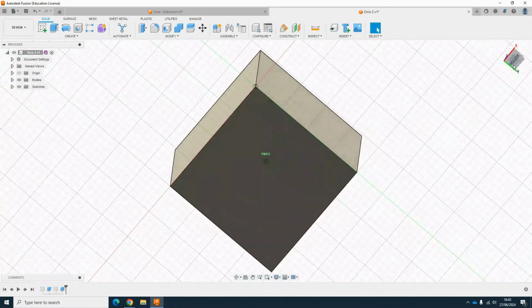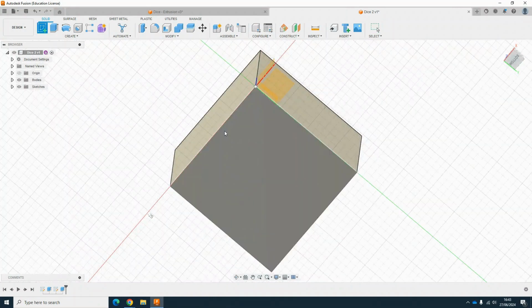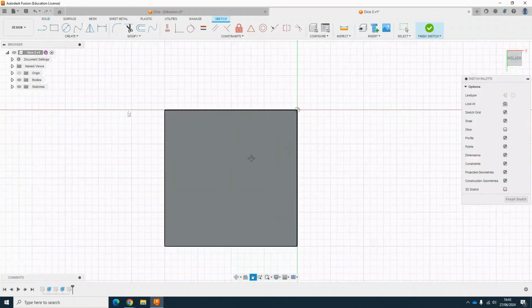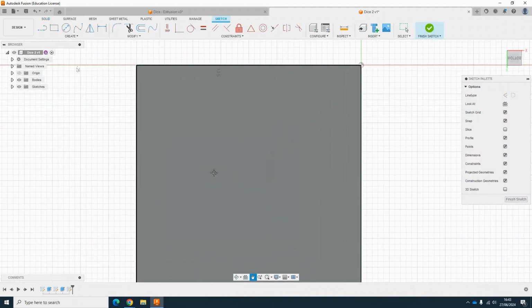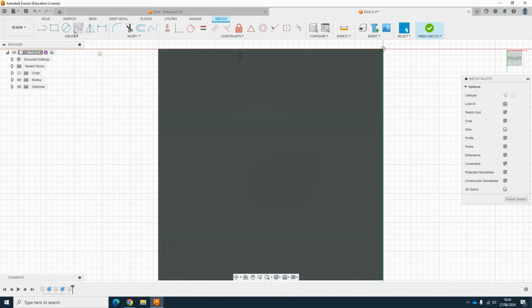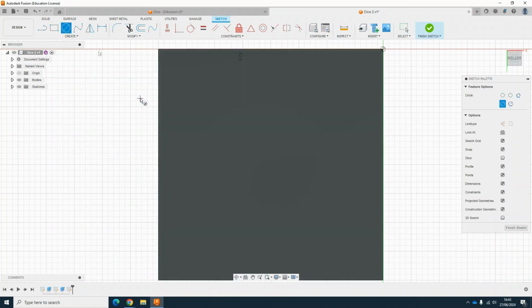So I'm going to flip over, I'm going to put the 6 dots on this side. Create sketch, select the surface, and then we're going to have a go at using the pattern drawing tool to create the 6 pattern more quickly. So I'm going to come along and it's going to snap to that point, and this is actually 5mm from there, 5mm from there, and it's snapping to it, which is really handy. 2.5,